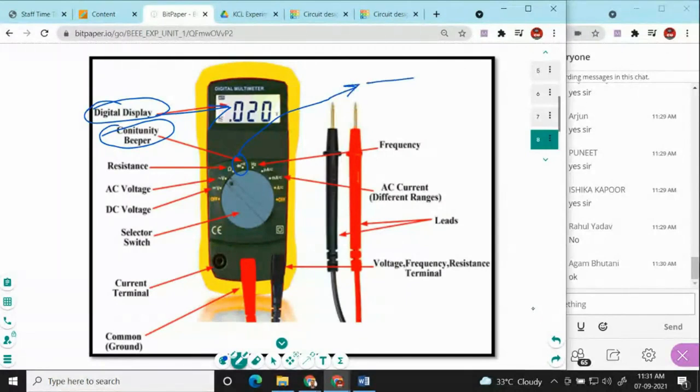Okay, let's suppose that this is our wire, and this particular wire is broken at this particular position. So how to check the connectivity? You have to connect one ground position to one terminal, and you have to connect positive to the other terminal. This is terminal 1, this is terminal 2, but this particular wire is broken inside the insulation.